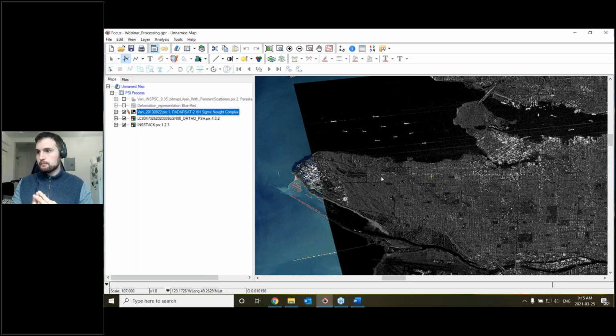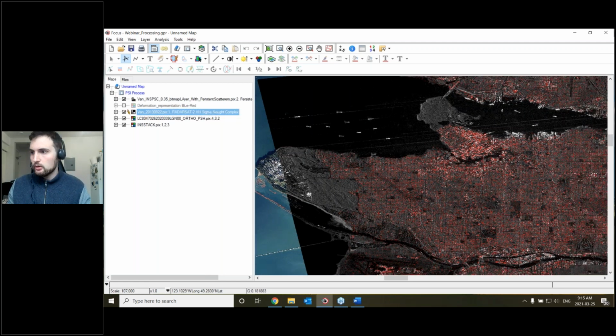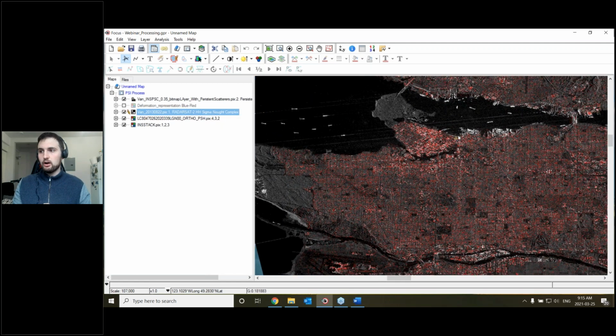Following that approach, the images were then ingested and co-registered between the pairs. And with these co-registered pairs, we were able to then identify the persistent scatterers based upon an amplitude dispersion method. And what we see here is the results as expected, where the points that are collected are behaving consistently across the multiple data sets, so they're not changing.